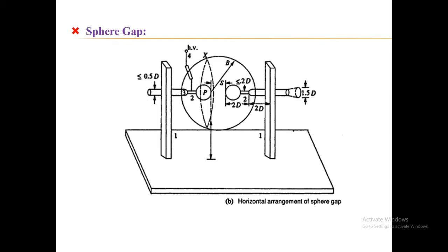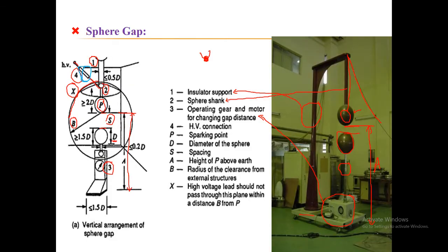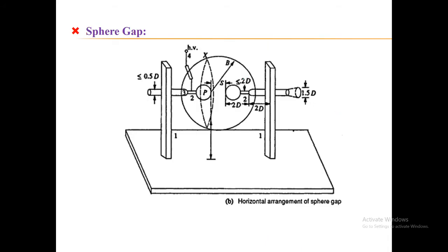So in that case, as you can see over here, as I'm increasing the voltage value, first and foremost requirement is I need to initiate the voltage at 1000 kV. So I need to avoid the premature failure or the sparking in the surrounding regions or sparking into the air, when I am increasing the voltage level and reaching 1000 kV.